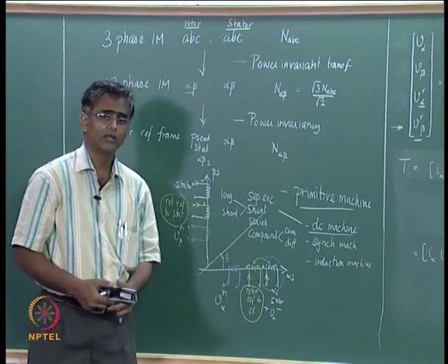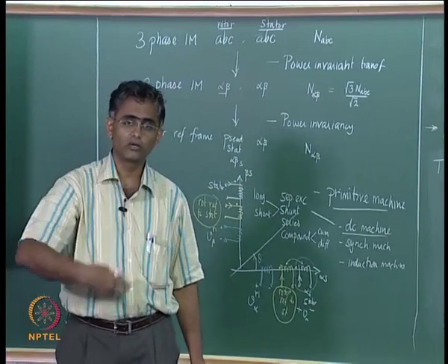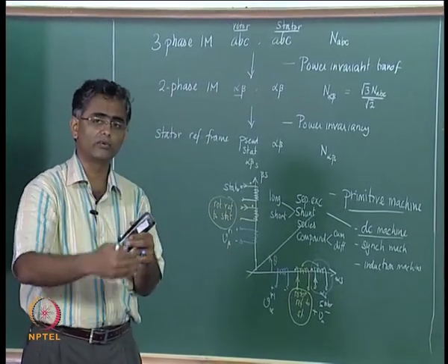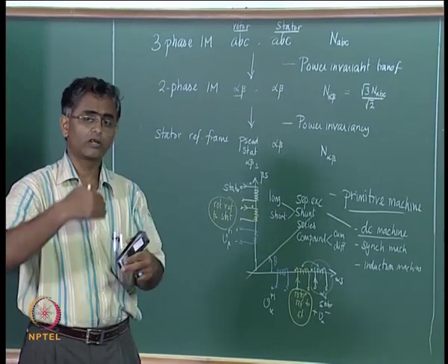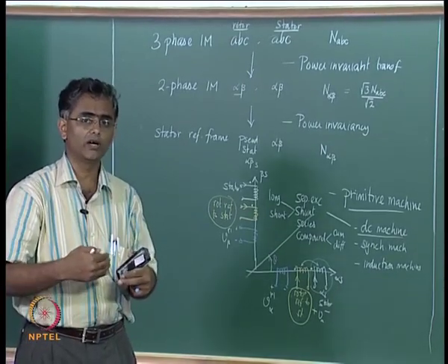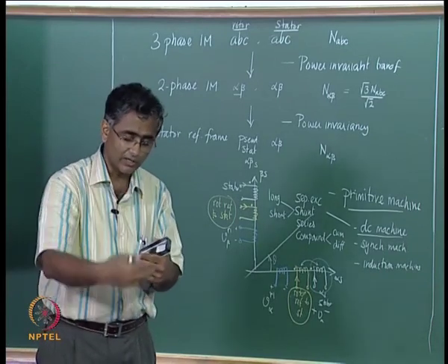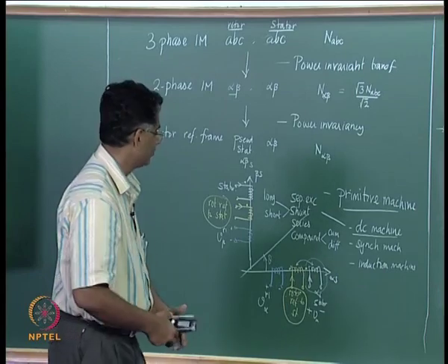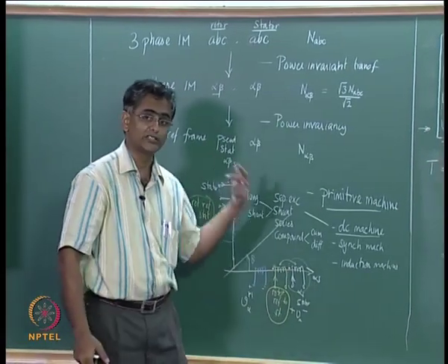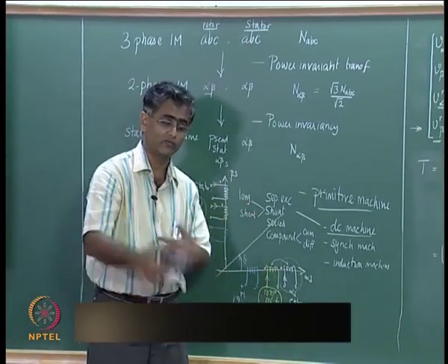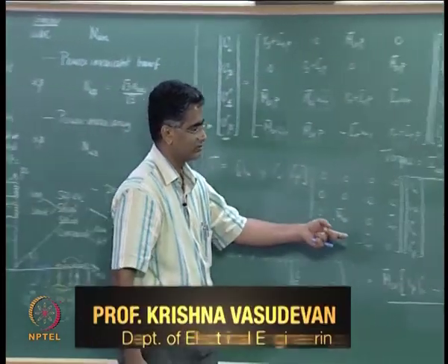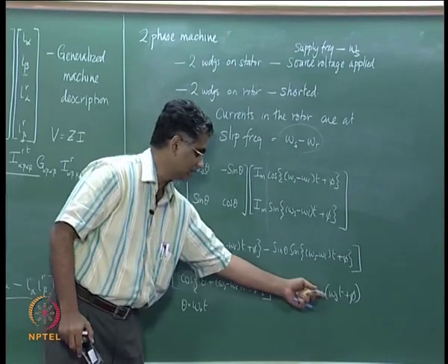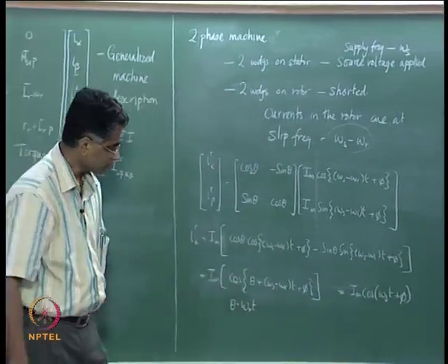The field generated by the rotor, if the rotor is fixed, moves at the slip frequency, but the rotor itself is rotating at omega r, therefore the net speed at which the field rotates as seen from the stator is at the frequency of the supply itself, the frequency of the stator field, and that indeed is the reason why the equivalent current now has supply frequency.